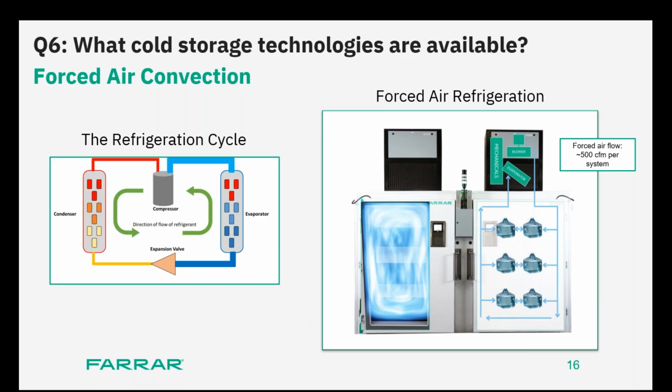So when the evaporator coil is wrapped around the chamber, right, the standard ULT. Now imagine that you're opening the door multiple times. And let's assume that you're talking about a high frequency of door opening application. Now, warm air will just rush in, right, even though your chamber is initially conditioned at minus 80, and then your set point temperature will change. So what's going to happen is over time, the air will get deposited, right?